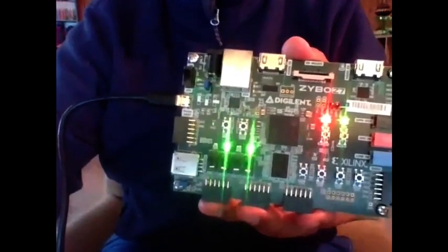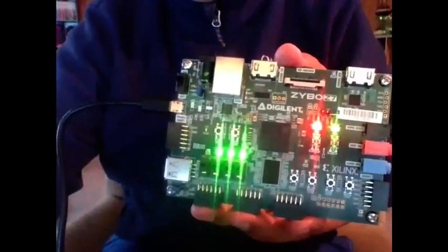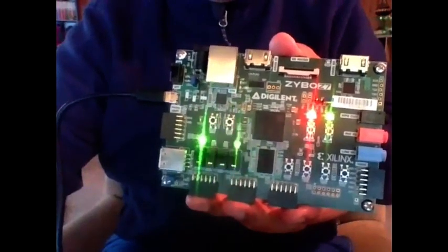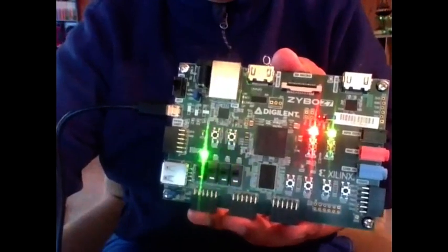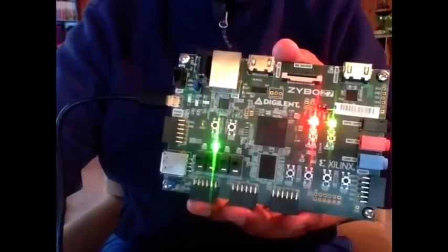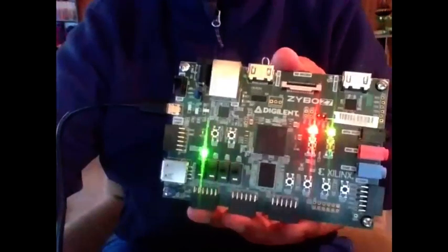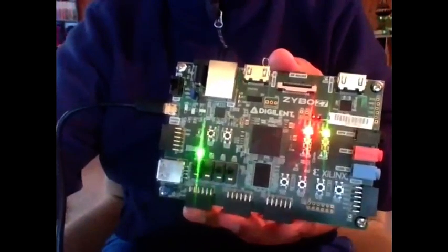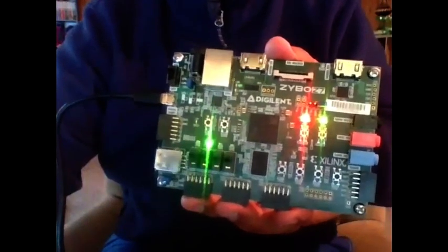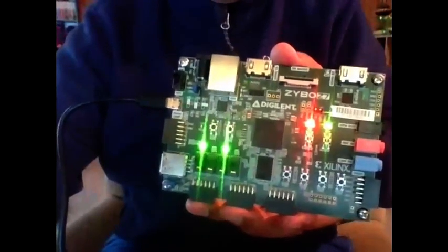Okay, and I can also do the following. I can now program a blanking bit stream, only the partial one. Here I go. You can see now how those two bits are off, right? But the other bits, 1001, they are still working. And finally, let's go back to the original one. I'm going to load the partial one for the app. And the counter app should appear now in a moment. Here I go. You can see them. Okay? And that's the example I wanted to show you. Thank you.